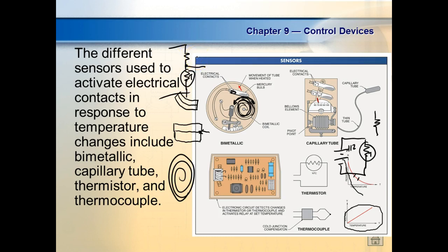So normally with these devices that vary their resistance, we have to put them in series with at least one resistor. And normally we put them in a Wheatstone bridge. Did y'all do Wheatstone bridges in DC? If you take sensors, we'll get into Wheatstone bridges. What a Wheatstone bridge does is it allows us to establish what zero is. So a thermistor would give us a certain resistance at a certain temperature, but what we'd like to do is be able to set a zero reference, right? You understand? So a Wheatstone bridge should let us set a zero reference. Calibrated, yeah.